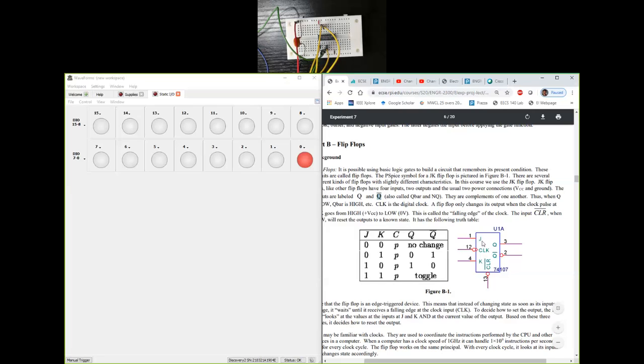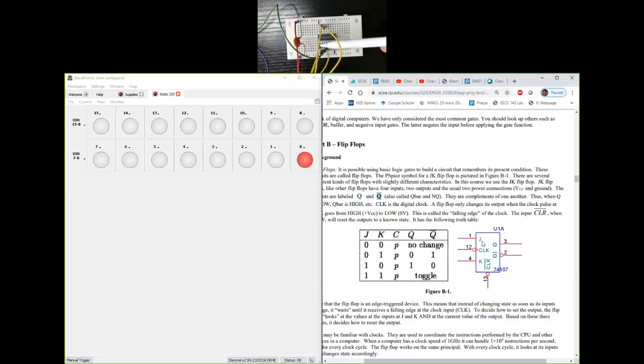Let's see. So pin number 1 is J input, and I have connected all the inputs in yellow, and my outputs are in green color at the very end. However, those yellow and green wires are connected to various different colors from the Analog Discovery. So the colors are pink and green and purple and brown, all various colors for the digital I/O pinout. So the way I've connected that is, for example, J, the pin number 1, I have connected that to brown stripe. Brown stripe is channel 11. So channel 11, I have connected that as J.